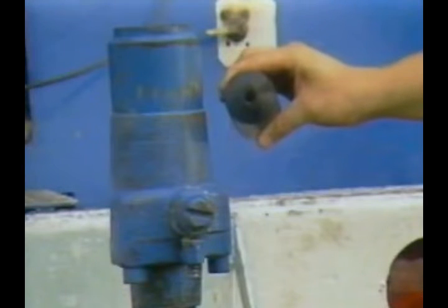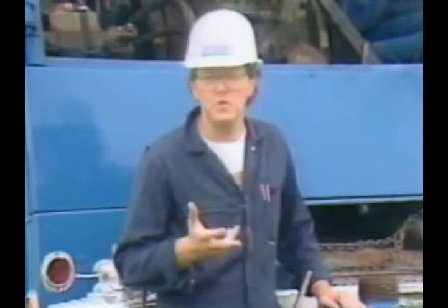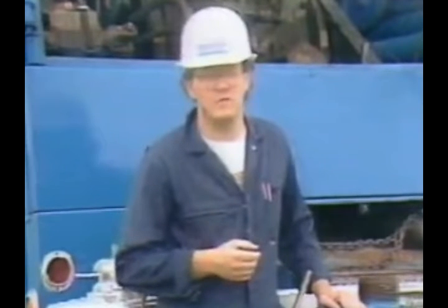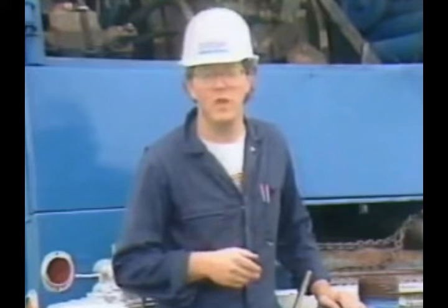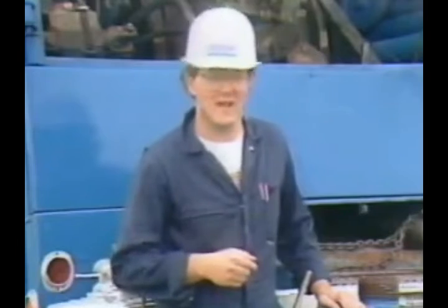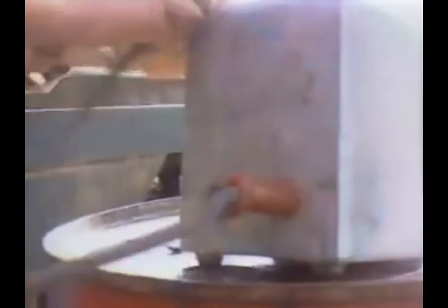In normal perforating situations, the pressure control assembly is either bolted to the blowout preventer stack of a drilling rig or bolted to the top flange of the tubing head or Christmas tree in through tubing perforating. The equipment is pressure tested after it's installed. After taking the necessary safety precautions to prevent stray currents from accidentally detonating the charges, a voltmeter is used to check for voltage between wellhead and truck.